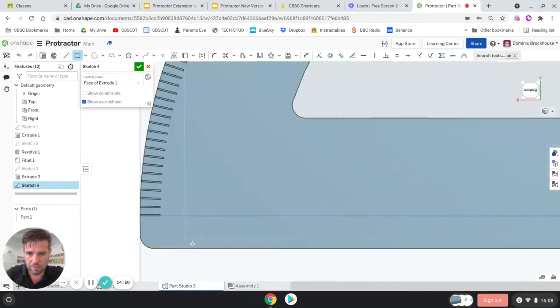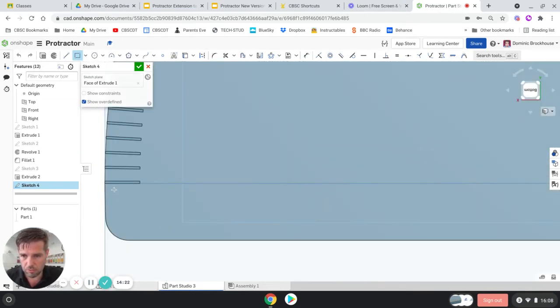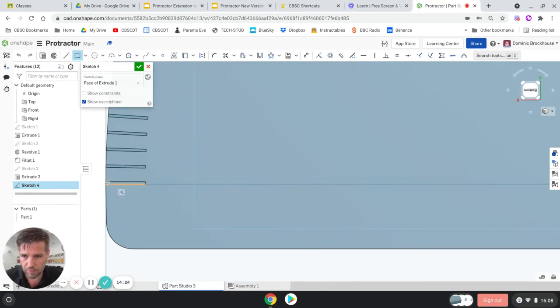Zoom in onto the left, and we're actually going to use the exact same starting point as the previous one. So it locks on, click and drag, and we actually want to get it to lock on to the same width. It's just going to be a bit longer, this one. So when it's locked onto the width of 0.2, the length, we can set that to be 9.